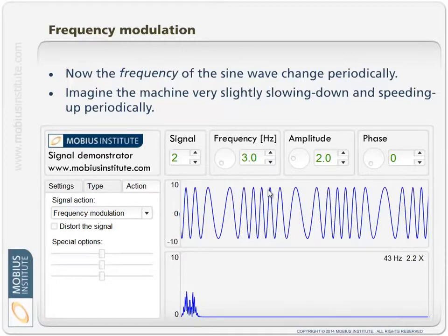So we get this variation in speed, which is therefore variation in the frequency. It's a periodic motion as each tooth comes into mesh, and we can see a variation occurring more at some points in the rotation than at others, and therefore once per revolution the machine can appear to change speed. Either way, even though this looks quite strange down here, we see lots of sidebands.